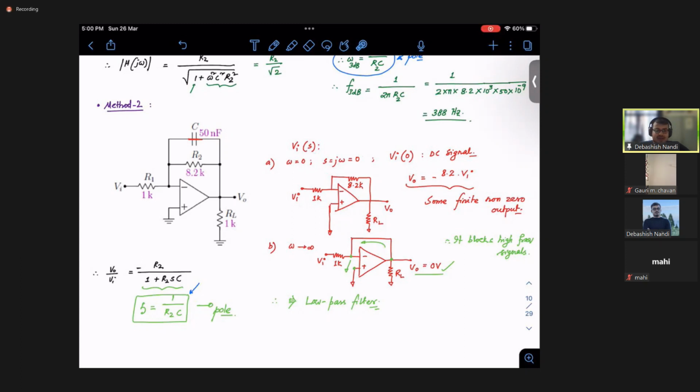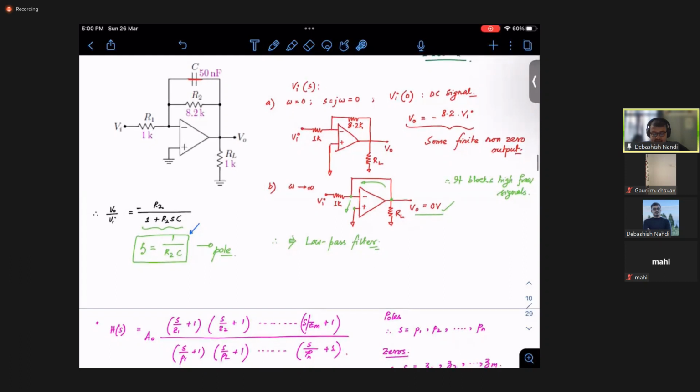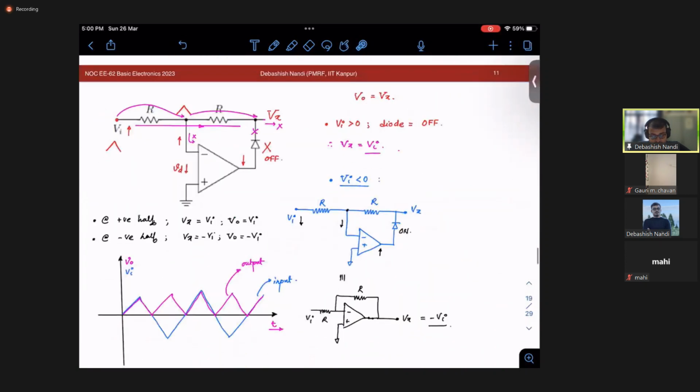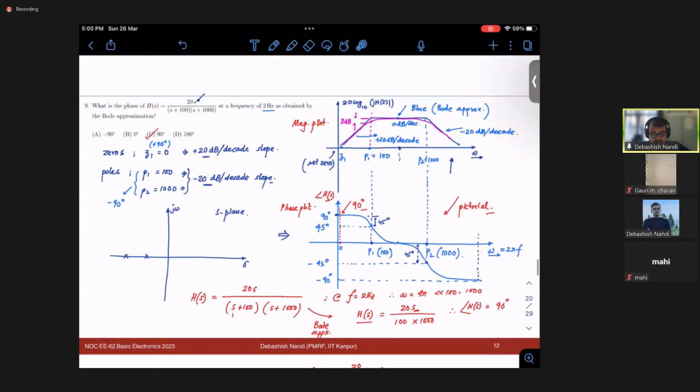And for the 3 dB bandwidth you can simply take the first pole location to get the 3 dB bandwidth. But this is the 3 dB bandwidth for low pass and high pass filters. For band pass filters it will be somewhat tricky, right? Because you need to, let me just go here. See, this is a band pass response, right? This response is a band pass response. So you need to find out this frequency where the 3 dB is occurring, omega L we say that, and this pole location, and the difference will be your 3 dB bandwidth, kind of, right?